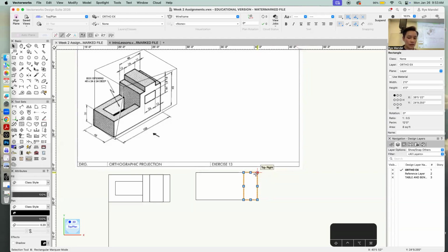Then I'm going to drag it over so that it moves to wherever I want. It's 12 inches as I'm seeing from the diagram. If I hit shift, it'll place it and snap it where my line is right here, but it'll also snap along this little red circle that I have. So that's how I got this rectangle to go over.